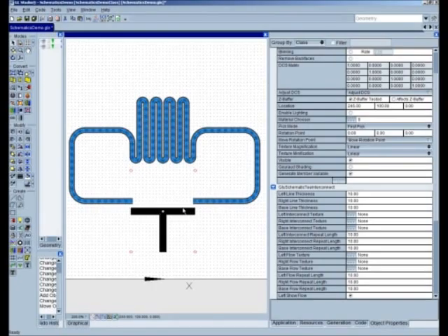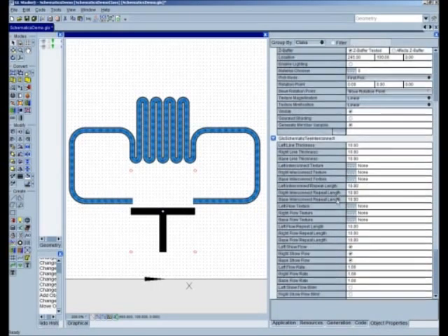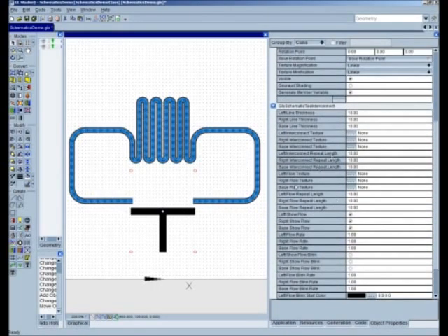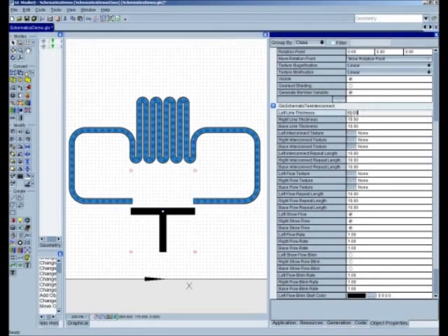The first thing we have to do, of course, is since the thickness was adjusted on the left and the right side, we're going to want to do that here. We notice with the T interconnect we have many, many more options, and that's because we can actually impact the base, the left side, and the right side all individually of each other. So the left line thickness, we need to set that down to 8. The right line thickness we'll also set down to 8.